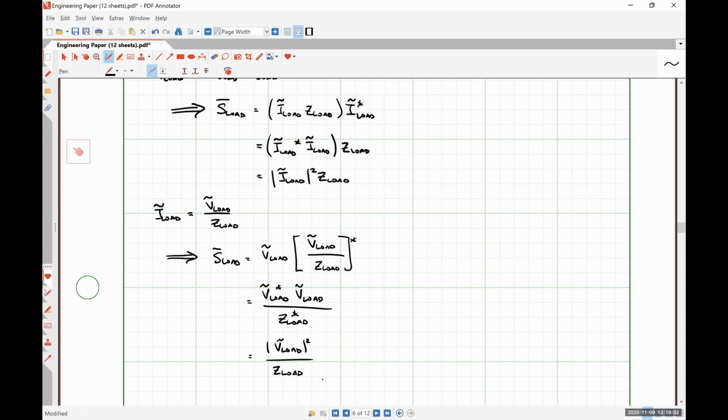So we again get a relationship where the only information that we need is the magnitude of the voltage, and that's enough for us to calculate the complex power. And then from that, we would know apparent power, reactive power, average power, power factor, etc. All of that information is buried in these pretty simple relationships. If we were so inclined, we could test any of these. So let's go ahead and do that real quick.